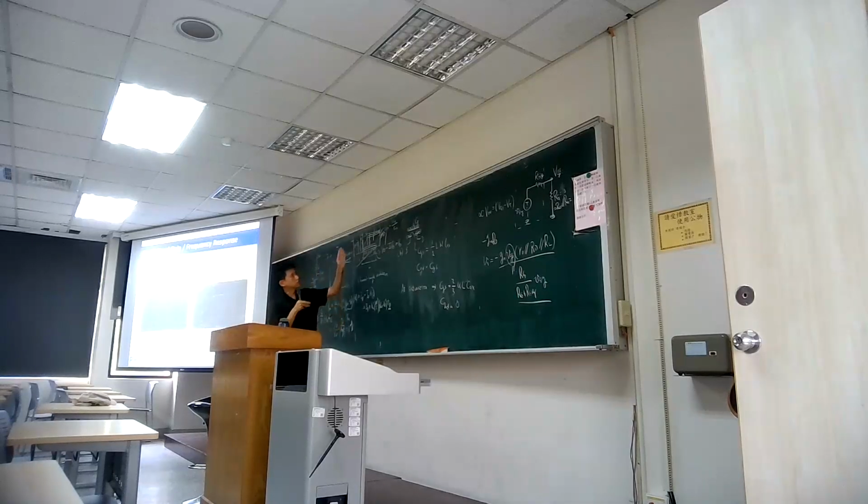If you get the separation between these connections narrow, you get large capacitance. Because the capacitance is determined by the area divided by the spacing between metal or between different voltages. If you get a smaller spacing, like in really fancy technology, 3 nanometer, 5 nanometer technology, the spacing between two connections is really narrow, and you get a large capacitance.